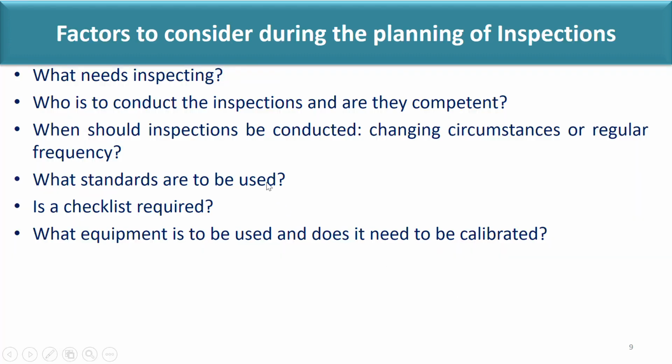Now, factors to consider during the planning of inspection. What are the factors that we decide or plan for the inspection? So there are some factors. What needs inspecting? Who is to conduct the inspection and are they competent? When should the inspection be conducted? Change in circumstances or regular frequency. What standards are to be used? What will be the standards? Is a checklist required? What equipment is to be used and does it need to be calibrated?